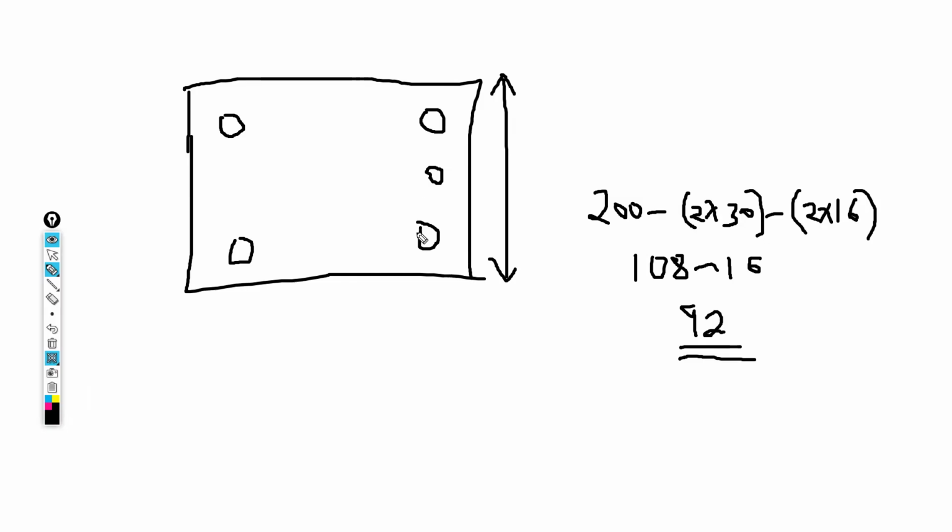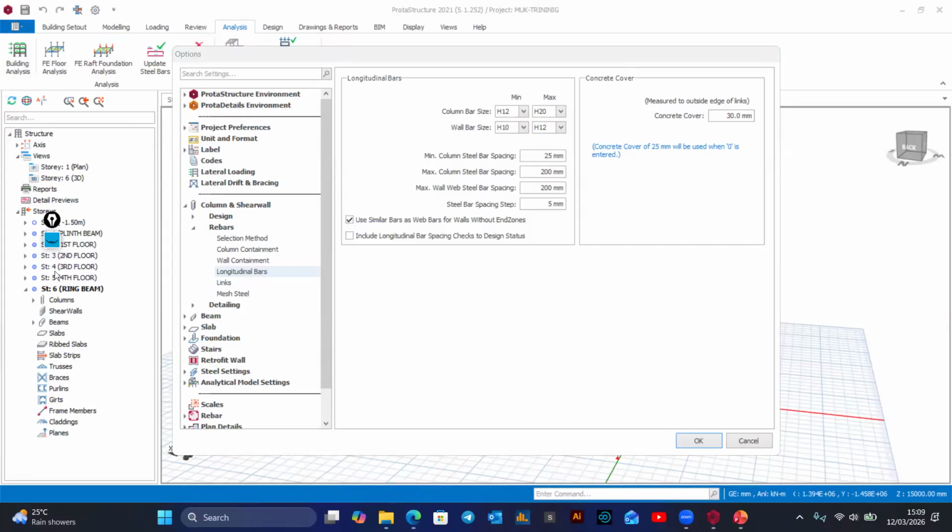Now, if you are to change this minimum spacing, the least minimum value you can have here is going to be the maximum aggregate size, add 5. That maximum aggregate size you need to follow up because it is determined at a stage where you are monitoring the workability of the concrete.